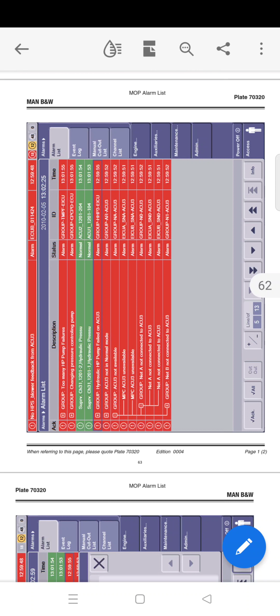Especially alarms interacting with the engine safety systems are common for the engine control system and the ordinary alarm system. As an example could be mentioned alarms giving slowdown or shutdown. When a slowdown has been detected by the external slowdown function, this is signaled to the ECS by a binary signal. When the binary signal is high, the resulting speed set point is forced to the preset slowdown level.